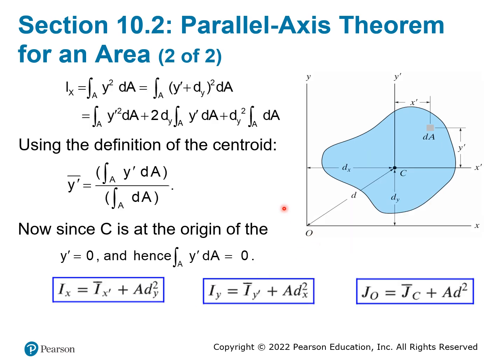All right, so let's look at the equation. How do we do that? If you want to find Ix, which is the moment of inertia of the area with respect to the x-axis, the definition is the integral of y squared dA.